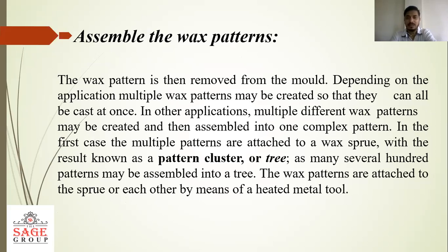Next step is assemble the wax pattern. The wax pattern is then removed from the mold. Depending on the application, multiple wax patterns may be created so that they can all be cast at once. In other applications, multiple different wax patterns may be created and then assembled into one complex pattern.